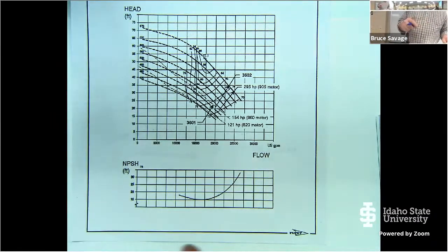Now I'm going to show you how to calculate the net positive suction head available here in just a minute. But a little word of warning. Two pump manufacturers, the pumps are identically the same on the performance as far as the head and the flow and the efficiency. One pump manufacturer says, I'm going to push that net positive suction head down as low as I can go because that's going to make my pump look like it is the better pump because I have a lower NPSH required. So be careful.